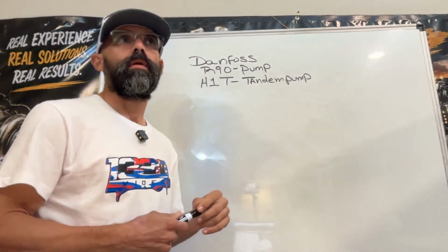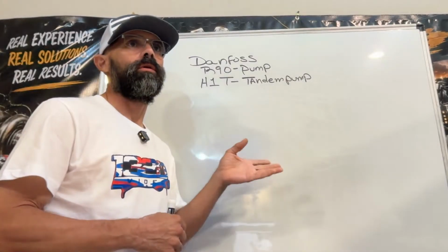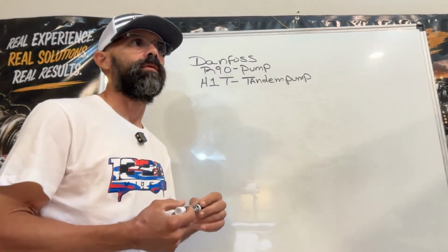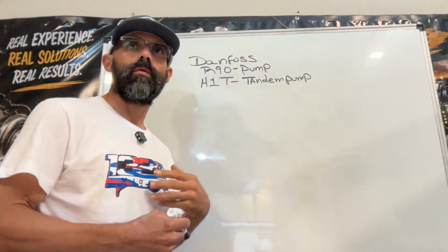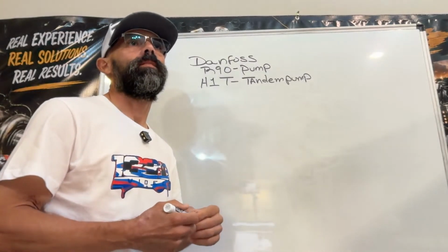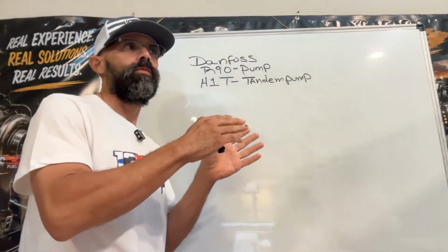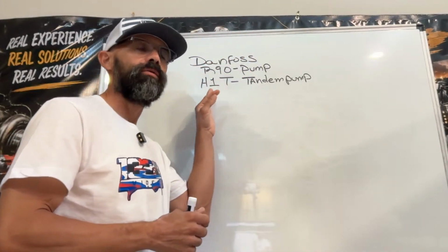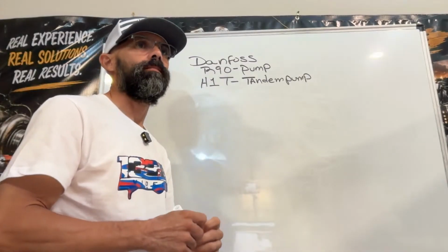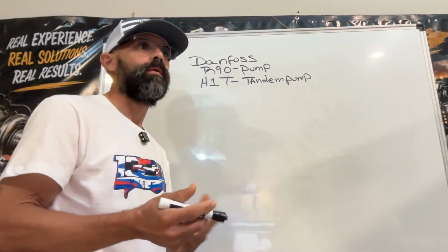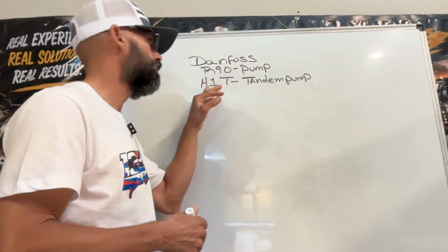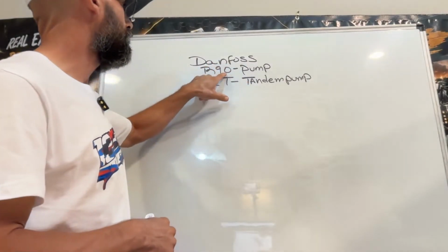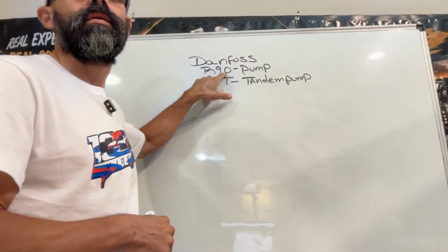Every system on that equipment has an R90 pump for your thrust and pullback, and the same R90 pump for the rotation, clockwise and counterclockwise, and for your mud pump. So basically, you can have 3 hydrostatic pumps on an 80 by 100. It could be 75 cc's, it could be 90 cc's, so the 90 stands for cc's.